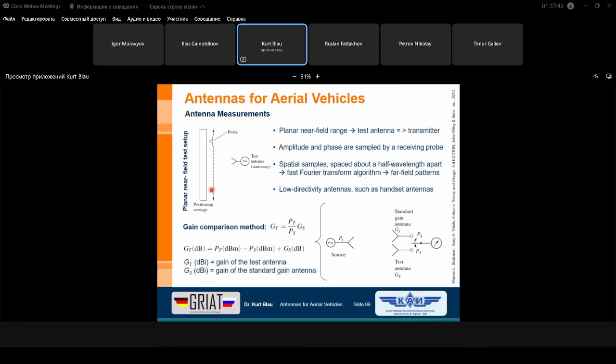And you can see here that such a planar near field test setup is very suitable to measure our microstrip antennas, because our microstrip antennas are very flat constructions, and so this near field test setup is very useful for measurement purposes of our microstrip antennas. And if you want to measure the back ratio, you can only turn around your microstrip antenna so that the antenna looks in the other direction.